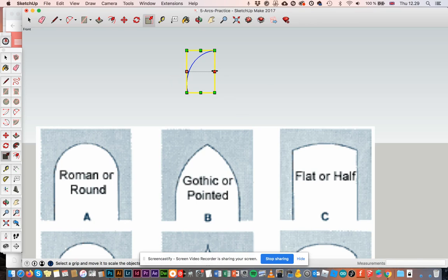So what this means is that if I want to create a mirror image, all I have to do is apply a scale of -1. So I can do this by eye until I hit the point. That's what I'm doing here. Or I can just type it in and say, start scaling it, and then change my scale to -1. There you go. And I've produced a mirror image.